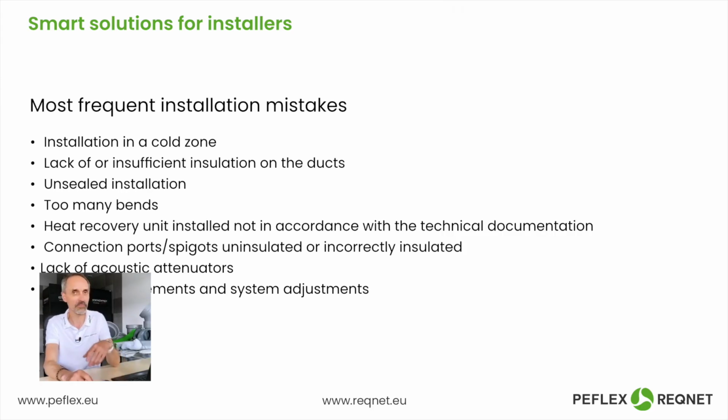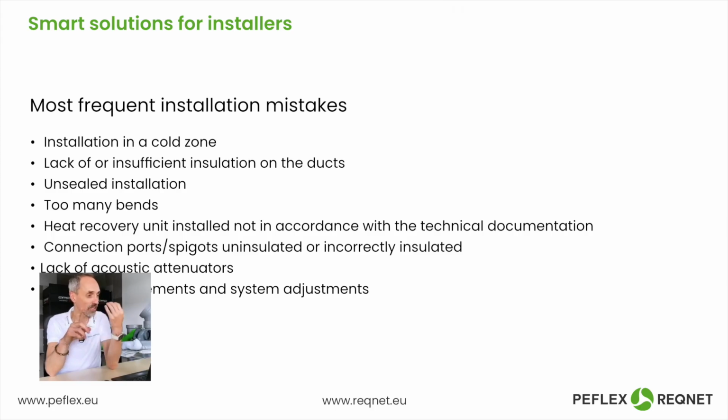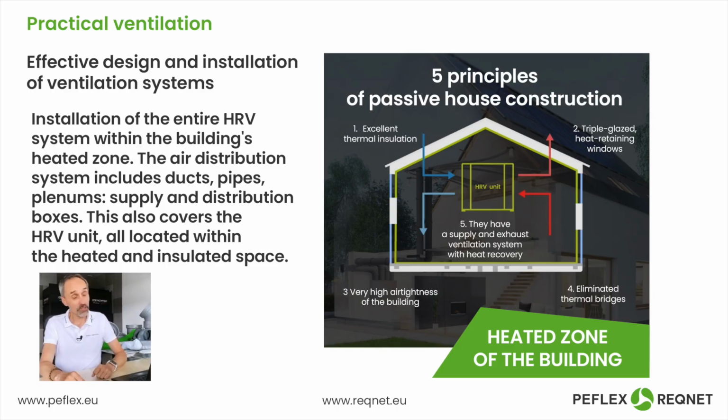This is related to a lack of insulation, poor insulation, or the ventilation system being installed in the wrong place. In other words, again, bad insulation. When it comes to noise, it's caused by ducts that are too small or not enough ducts, right? So the air comes out at too high a speed. So those are the two main issues, noise and water, right? Or low temperature. That's what I mentioned earlier, just as a reminder, right?